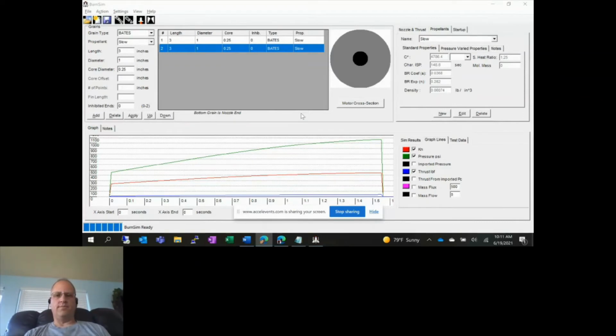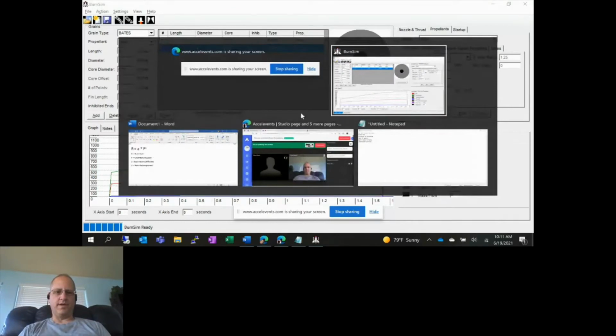You'll have a pressure transducer in there to measure pressure. So in a perfect world, you'd have a hockey puck that's 1 inch thick, with one surface that burns and the rest of it inhibited. You have a pressure transducer in there. You can light that motor and measure the pressure in there, and you can control the pressure by choosing nozzles. So you do one test with a large nozzle, and you'll get one data point, and do it again with a little bit smaller nozzle, get another data point, and you get what you need to characterize your propellant.